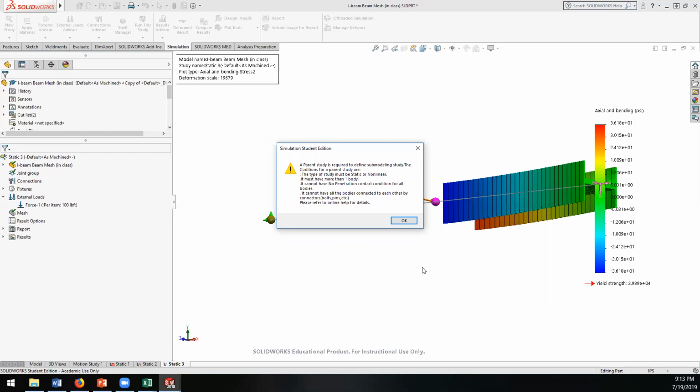I would pin it at the frame. Who cares about the frame, right? And then do the sub-model. In fact, you could put the frame in there, but if you just did sub-modeling, it would get the loads at those other bodies and then run an analysis on that. Yeah.